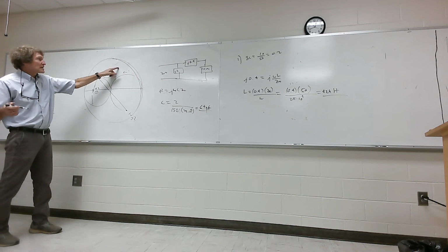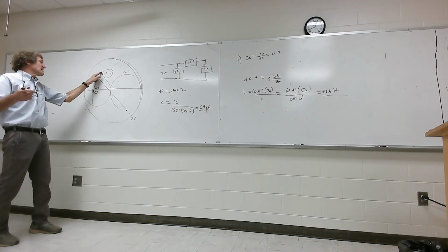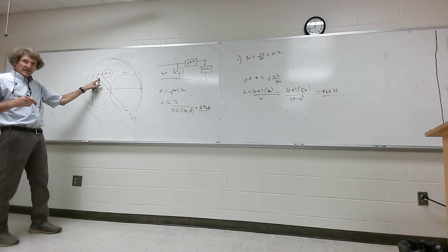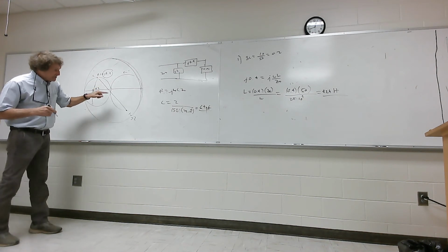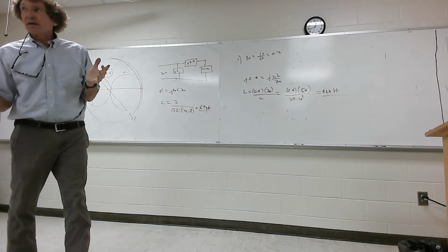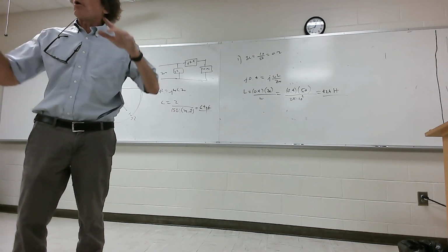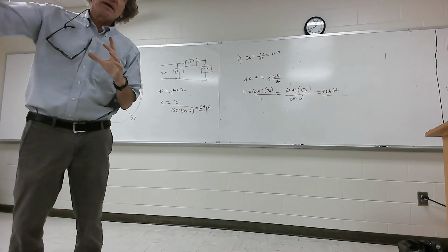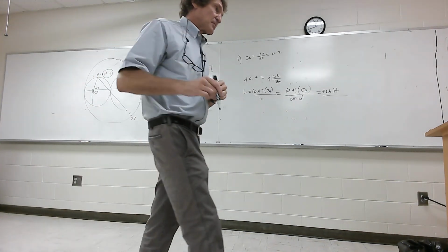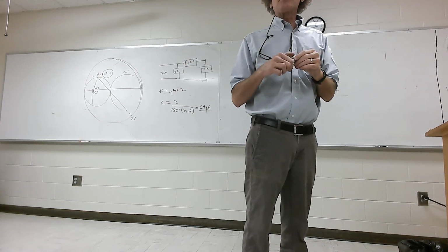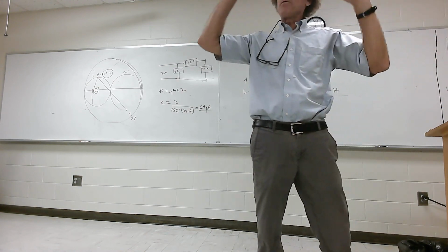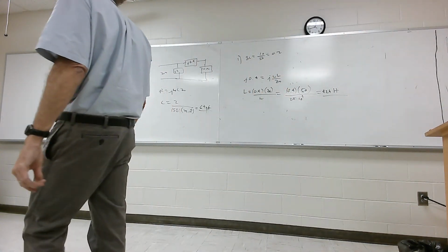So what I can do is, if I'm here, I can add something and get to this circle, the rotated one, and that would be in the impedance domain. Y'all follow me? Then once I'm there, I go to the admittance domain and I add something to get to the center. But if you're outside, keep both of them. You always go to the rotated circle, and then you go to the other side to get to this. So we'll do some of those, but trust me, I think you'll see it. Remember those trajectories. You move along the real part of the trajectory all the time by adding or subtracting.